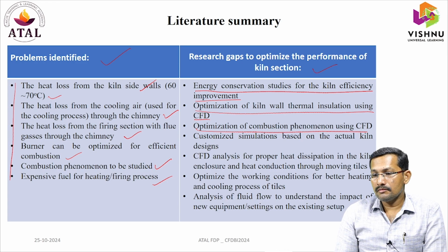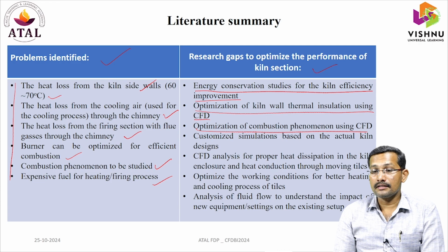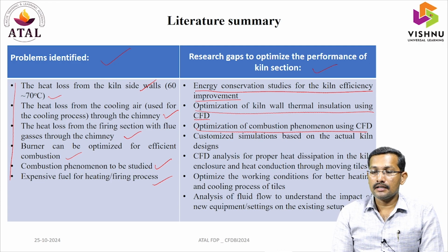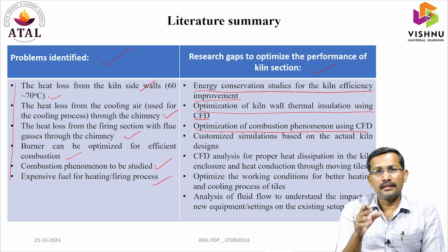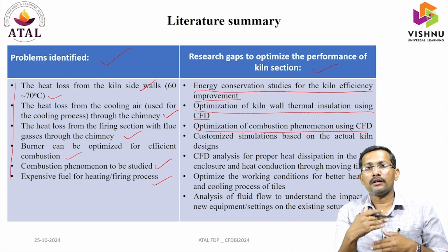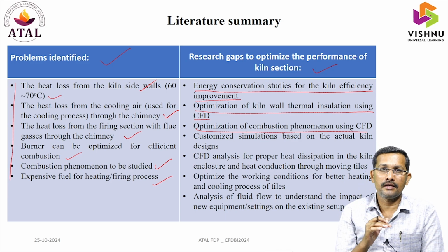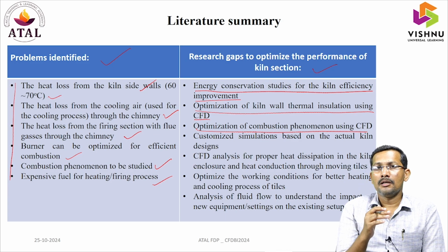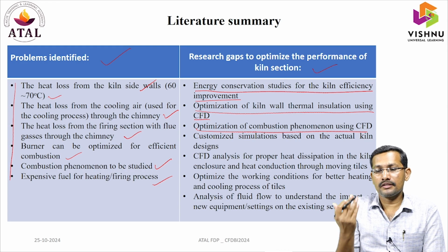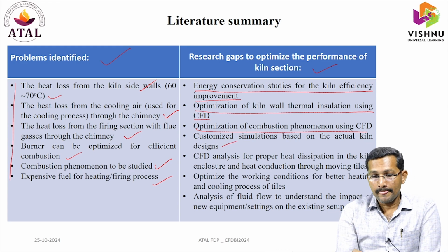Next, customized simulation based on the actual kiln designs. Initially we will take the actual kiln design, like how many modules are there, how the burners are placed, what the burner design is. That is the actual kiln design. But we may suggest some better designs based on the CFD investigation.